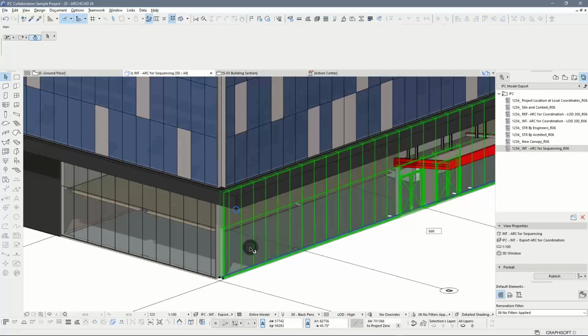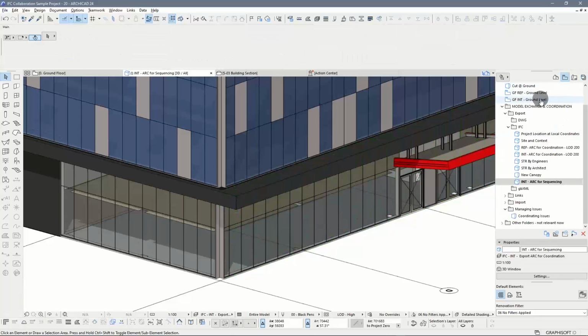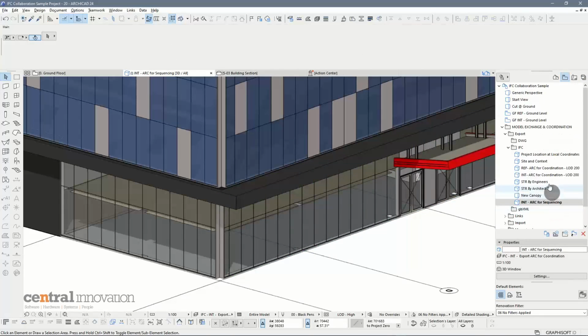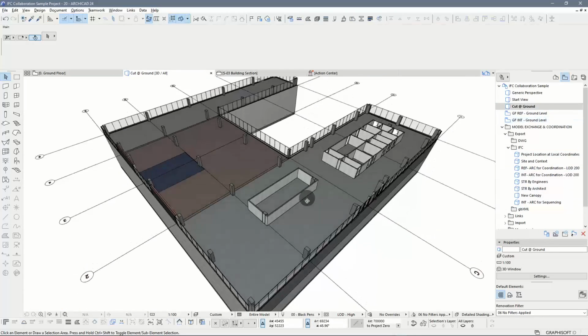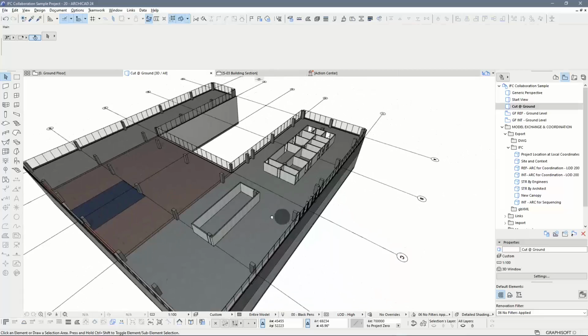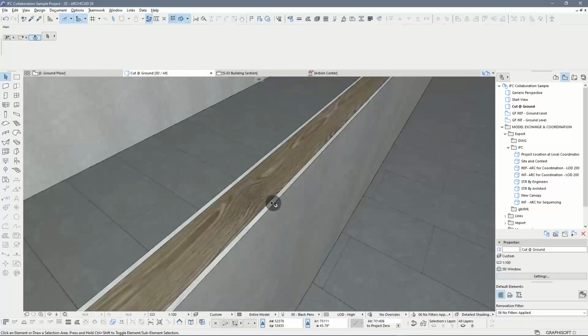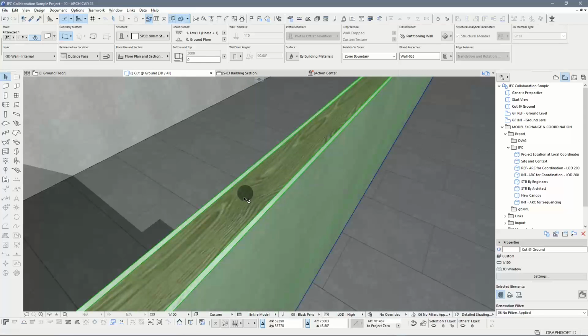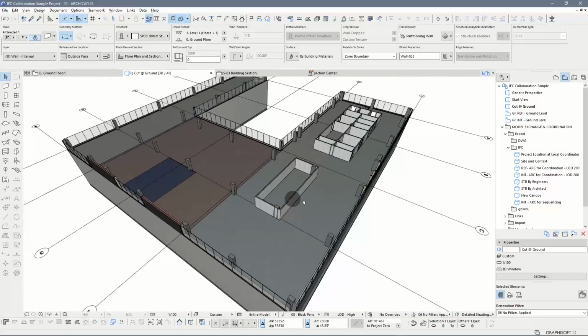For that, you build curtain walls that have a bunch of sub-elements, but are essentially a single element. If I take a look at the ground floor in a cut view, you will use composite walls, timber stud with plasterboards on the side, which is a regular way to build relatively complex elements within Archicad.